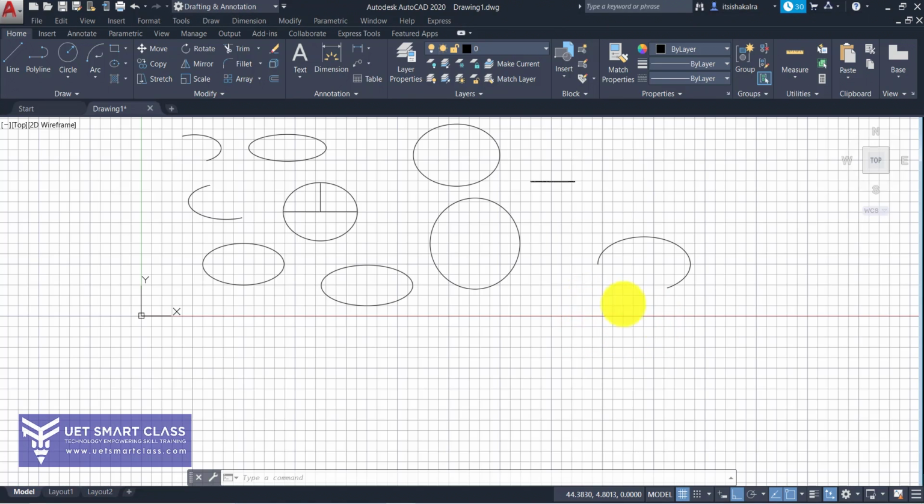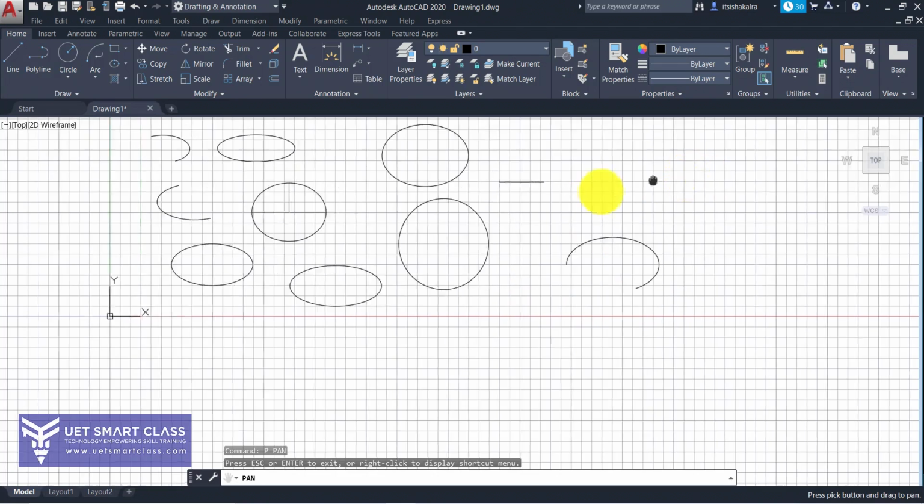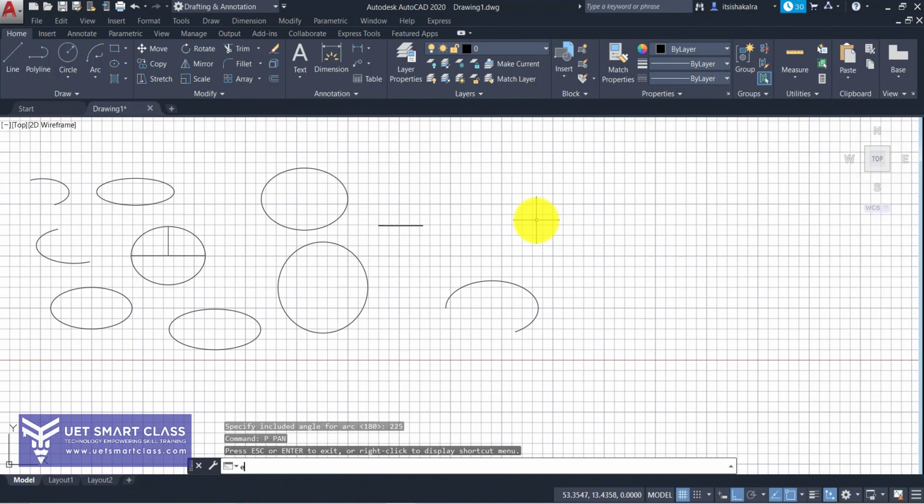Now the third is through parameters. The same thing, EL enter, go into the arc and create an ellipse first, and then click on parameters. Rather than specifying your angle, click on parameter. Parameter is nothing but the parametric vector equation, the calculation of ellipse by the software in vector equation. Okay. Now here I have to specify two parameters.